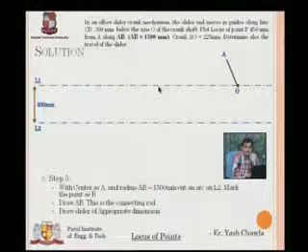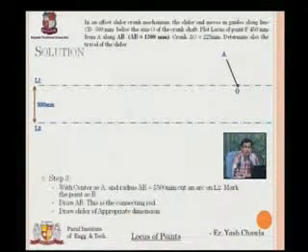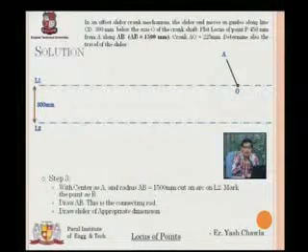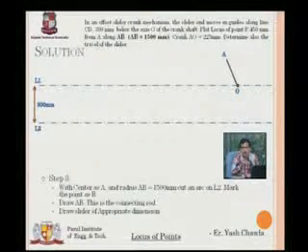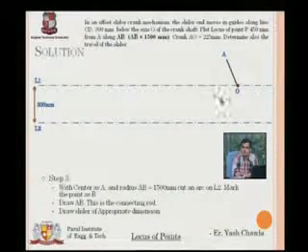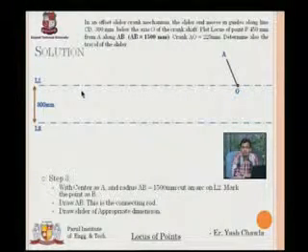Now the difference between the previous question and this question: the radius we have taken already, the 1500 mm, and we have put the pointed end of the compass on A, and now we have to mark the arc. In the previous question we knew that the axis of rotation of the crank and the reciprocating slider were both on the same line.